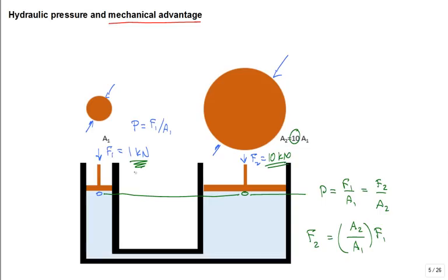Very powerful hydraulic systems. So what principle is used in hydraulic systems? Pascal's principle. What's it say? Confined fluid. If I boost the pressure in one area, the same pressure increase is felt in another area. How do we use it? Change the areas of pistons, and now you have a significant mechanical advantage.